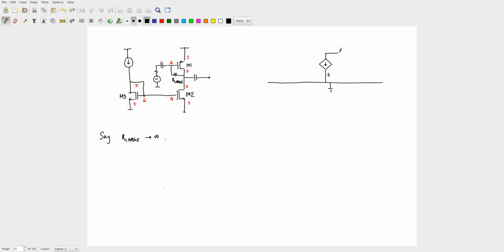The drain, okay, we don't know what about it. So let's only take this guy. It is going to have its R. It's a PMOS device, so I'll call that RP. This is basically the channel length modulation resistance corresponding to the PMOS device.